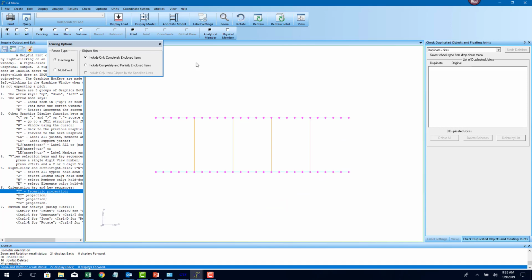Now, from the geotechnical reports, you might have a subgrade modulus that you might want to assign to the mat slab. In this case, there is a feature inside GT STRUDL to generate those spring constants based on influence areas of those joints. I'm not going to go through that in this tutorial.